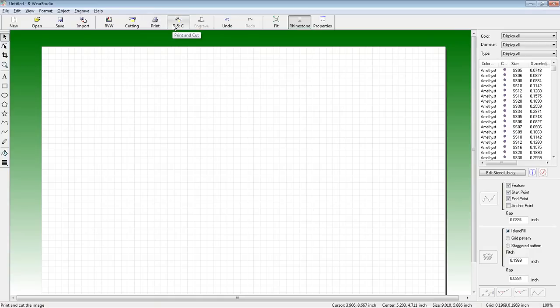This is if I want to do a print using, say, a desktop printer like the Brother that I have hooked in here with some inkjet paper or some laser toner paper. And I've got those types of transfer mediums. I can set this up with the registration marks that I could then take that paper back over to the GX24 and have it find those registration marks with the optical eye registration and cut out the design there. And we'll show how to set up those cut lines in here.